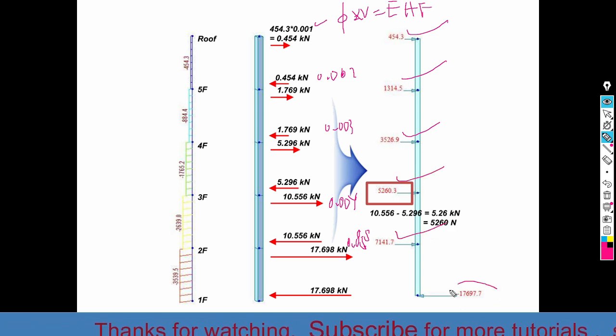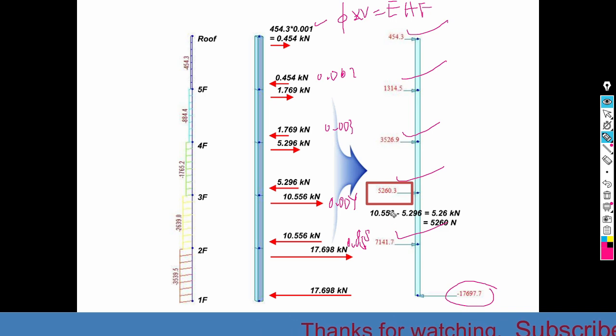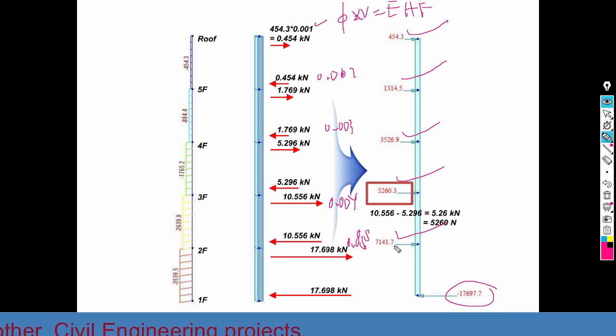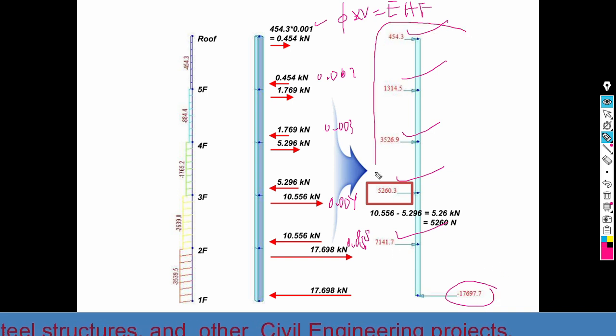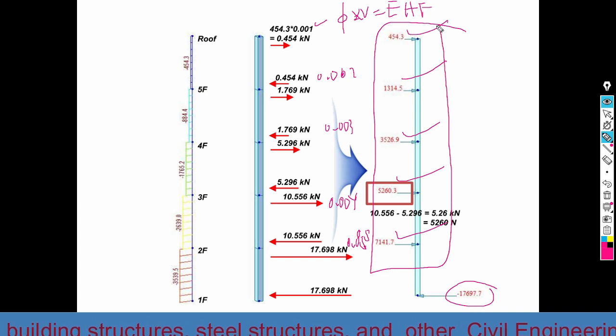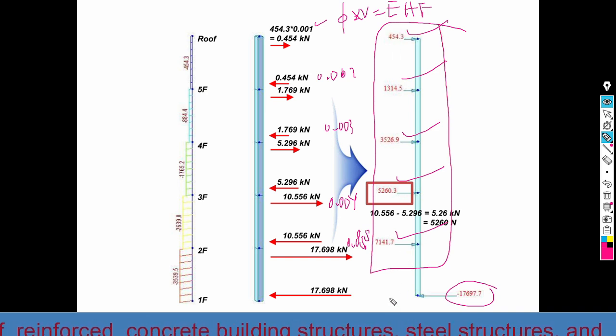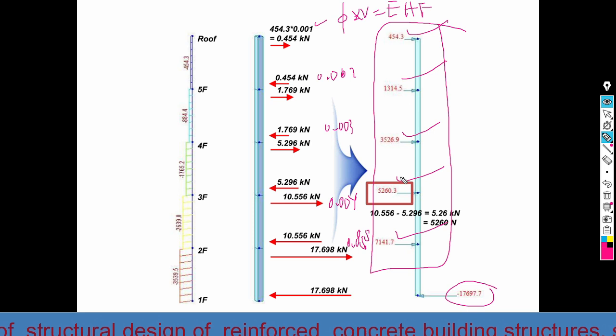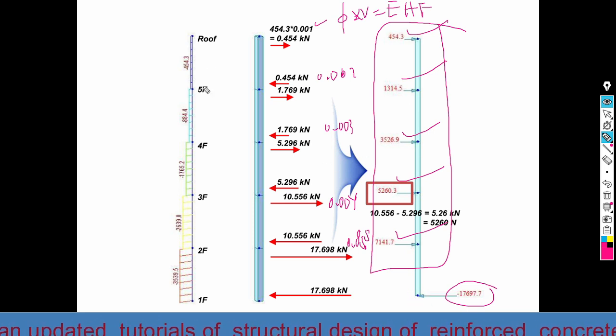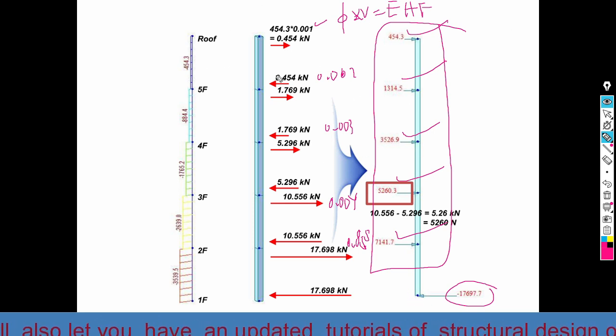Like this. And this one is the reaction force, which is the summation of all those forces. So this force will not be applied in the model. The only nodal forces which are going to be applied in the model are those forces. So this is for one column. For all the rest of the columns, in a similar way, we can apply the nodal force.